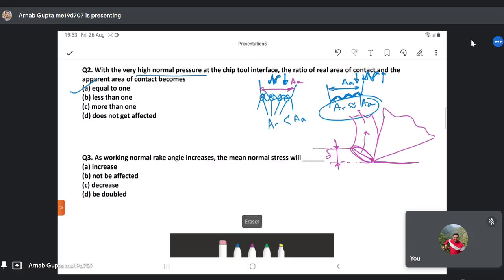Now as the material is flowing on the tool, or the rake surface, to be more particular, this will be the contact length after which it separates out from the surface of the tool and it flows away. So from this point to this point, you can see the above phenomena, that is the sliding and the sticking zone, prominently taking place here.